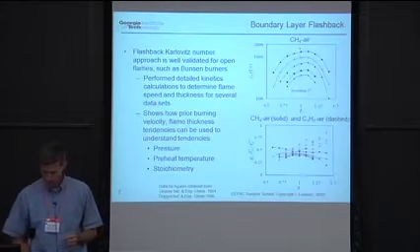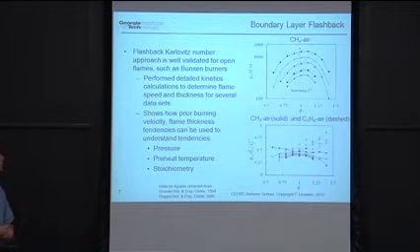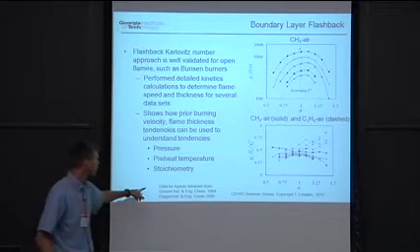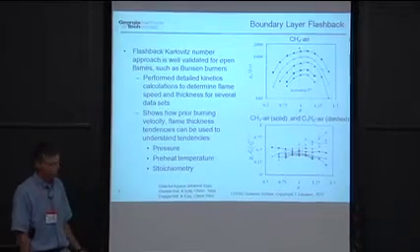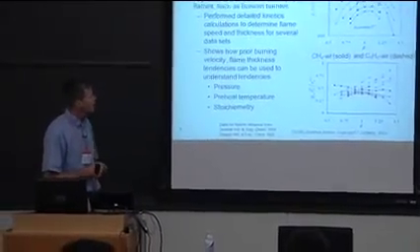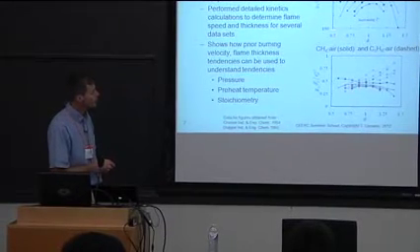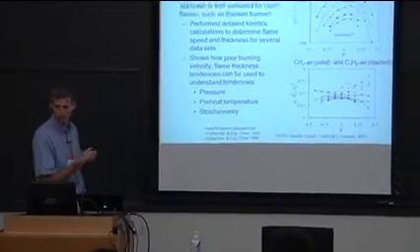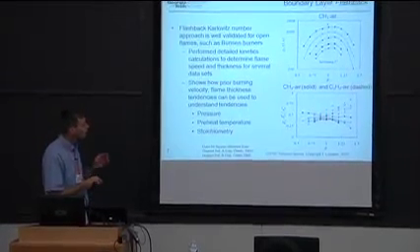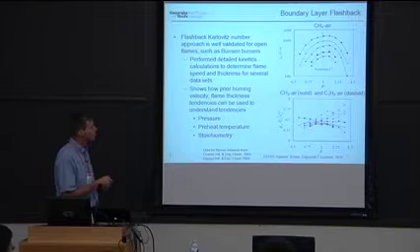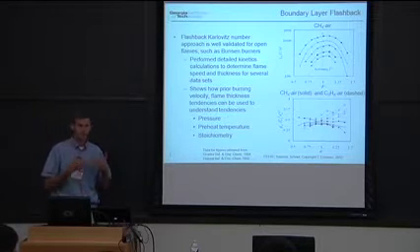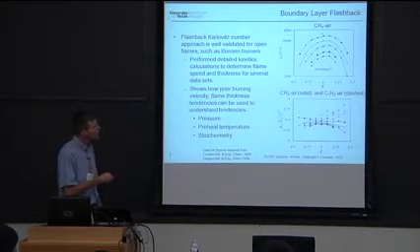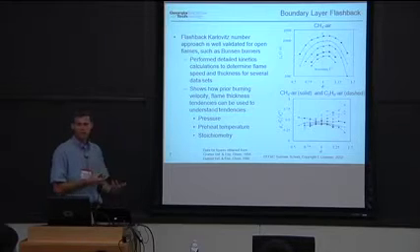This basic idea is very well borne out by experiments in open flames, such as Bunsen flames. To illustrate this, we pulled a whole bunch of very classical flashback data from the literature, from these references. These authors measured critical velocity gradients, g_u, as a function of phi, and at different preheat temperatures. T_u denotes the temperature of the unburned reactants. As you might expect, for a given preheat temperature, the critical velocity gradient is highest at an equivalence ratio of 1, because the flame speed is higher. You've got to have the highest velocity gradient to keep the flame from flashing back, and then it falls off on both sides. This roughly mirrors the dependence of the flame speed on fuel-air ratio.